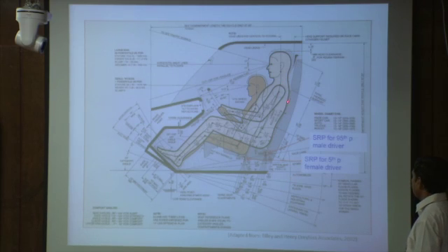So accordingly we have to position the human model based on the different types of reference points. Here: accelerator heel point, H point, SRP. Based on all these reference points, we need to position the human model correctly on the seat.